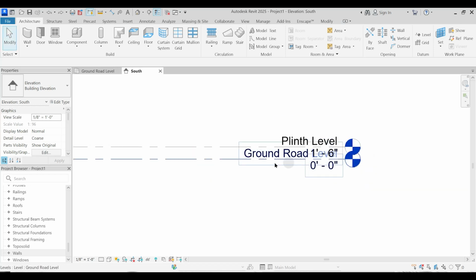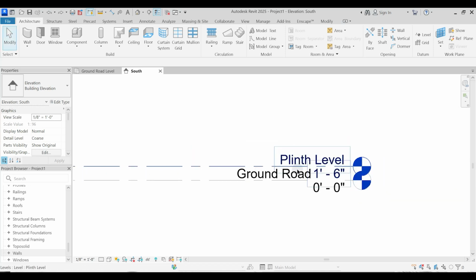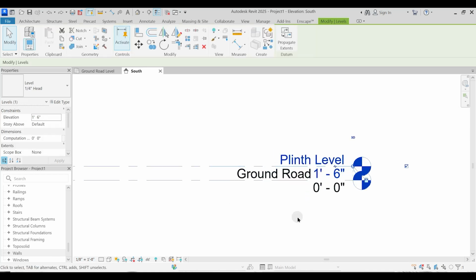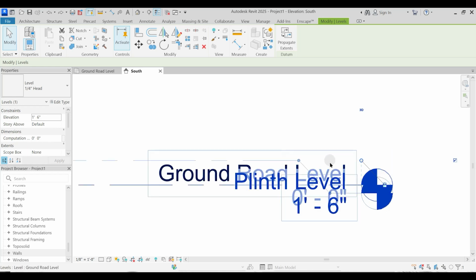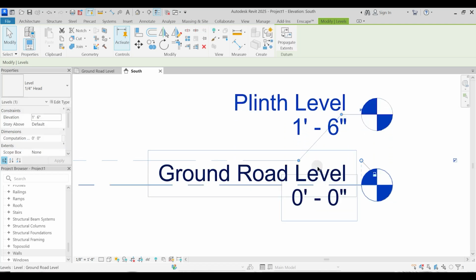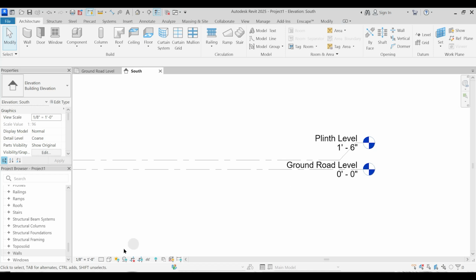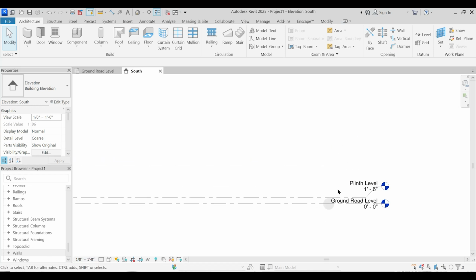Let's say that if this is the drawing and you want to take out the printout in this scale only, then another option is to select this particular level. As soon as you select it, you see this elbow, this paper clip icon, and it's called Add Elbow. With this, I can select this and drag it upward. And with the same scale, 1/8 of an inch equals 1 foot, now visually both of them are visible properly. Okay.